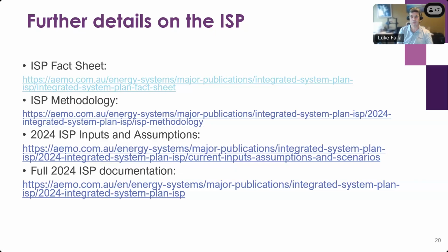Mm-hmm. And Julie Jen asks, is convergence an issue for the load flow cases? How long did it take to solve them? Yeah, it is a big issue, and that's why we end up doing snapshots, because we need to go through those one at a time and see why it's not solving. All the time it's voltage stability issues, because you're looking 20 years ahead and the load is much larger and you haven't built out the distribution network or your voltage planning. So that is a difficulty for us.